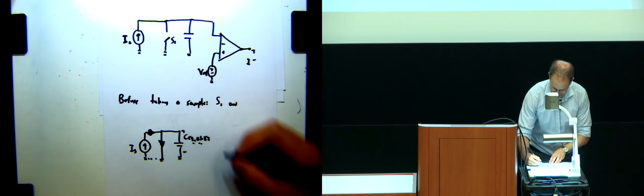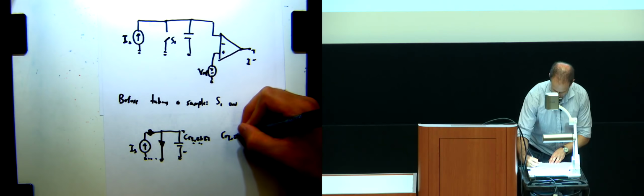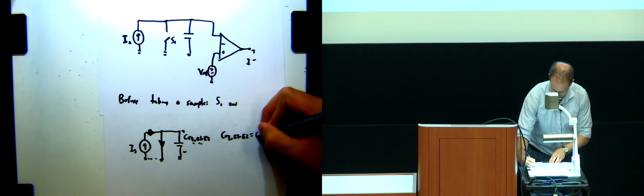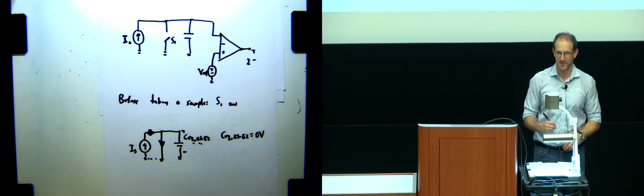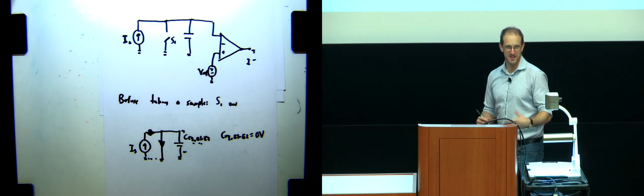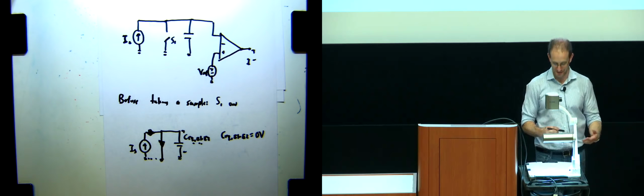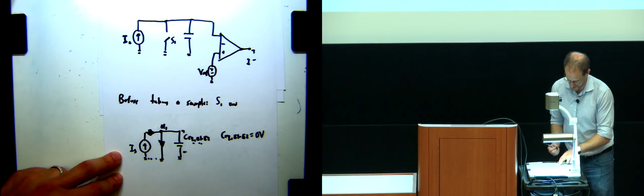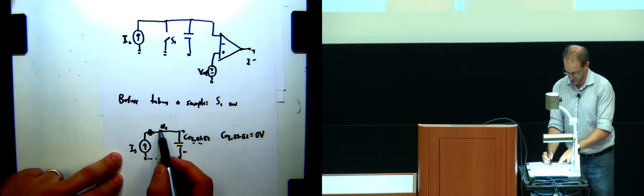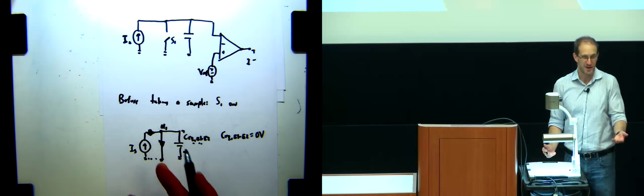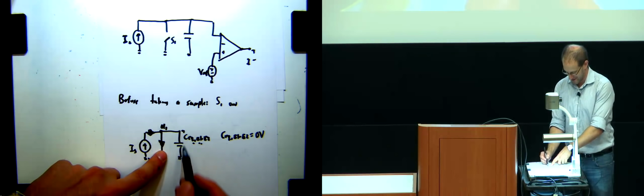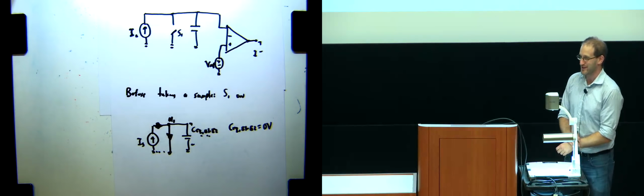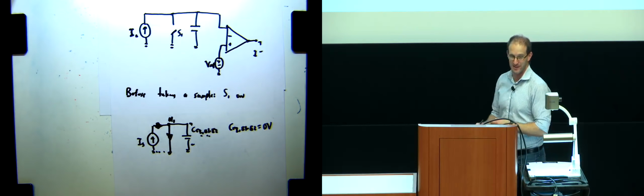So everything is now set up so that the voltage across the CEQ here is going to be equal to 0 volts. And again, if you don't see that, and you're more used to the linear algebraic method, you can work that out, but there's really just one node in the circuit, right? There's just a U1 here. If I put a short circuit between U1 and ground, that means U1 has to be equal to 0 volts. Notice that is also the exact same voltage across the capacitor. That's how I came to this so quickly.